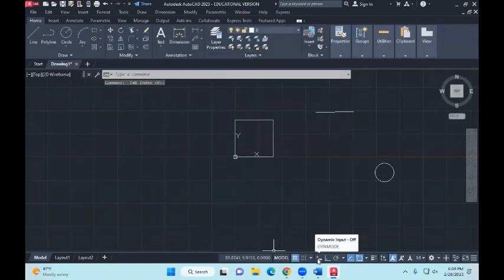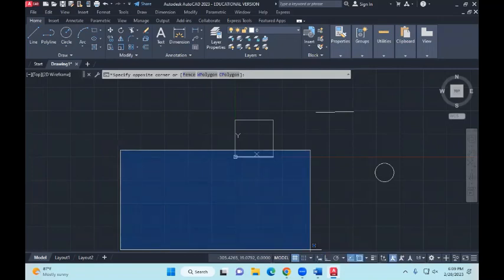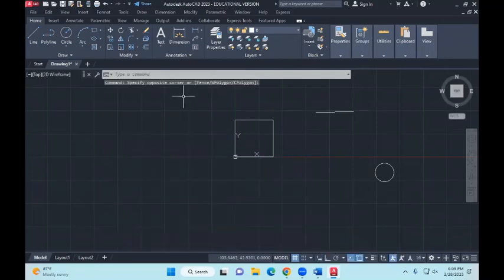The next one is dynamic input. So I asked all of you to leave it off. So what happens if you turn on that button? You are having an option to input things near your crosshair, right? If you have dynamic input turned off, your only option of giving an input to AutoCAD is through the command area, the dashboard and the toolbar. Okay, got it? So your crosshair is clean and nice. Nothing is over there except for that cross.